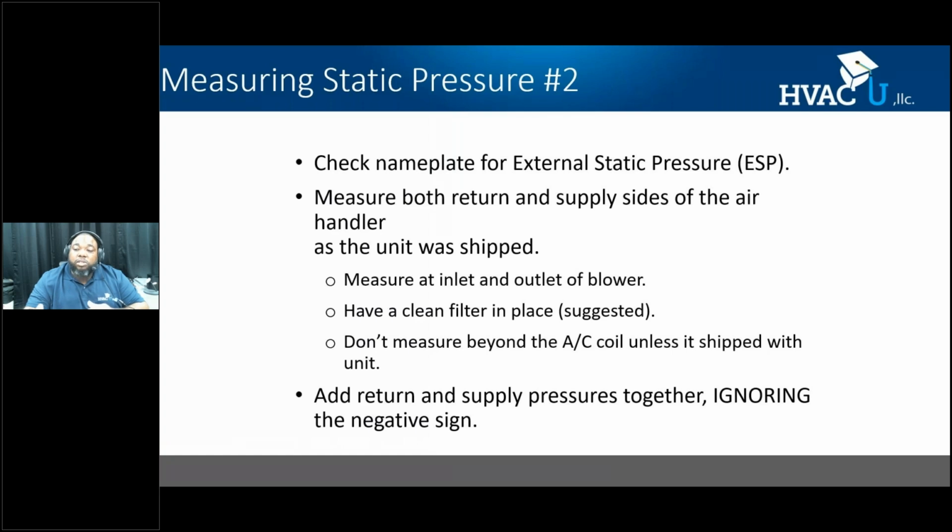And if you're going for external static pressure, remember you want to test the equipment as it's shipped. Now, you can use static pressure for troubleshooting, which is outside of the context of this presentation. But external static pressure gives you a lot of information with one reading. Most of the meters on the market today, you can hook up 2 probes, and it will give you an external static pressure reading.